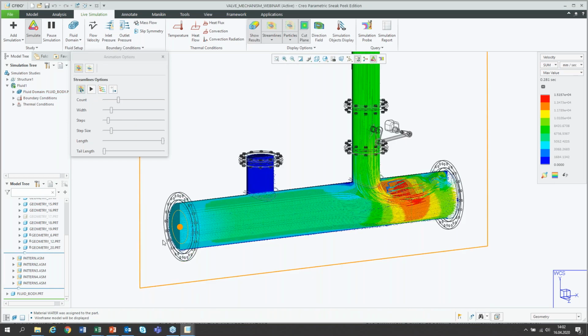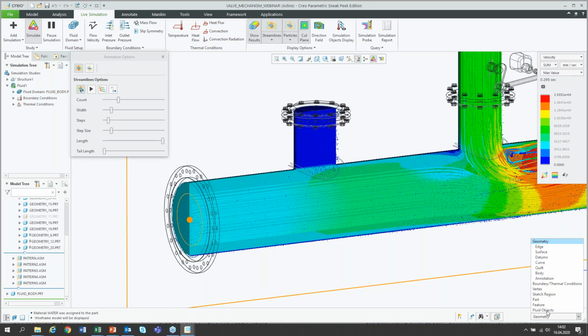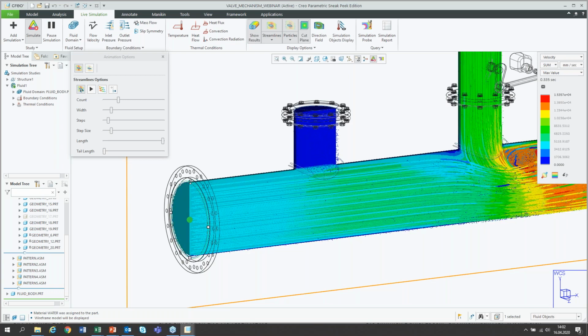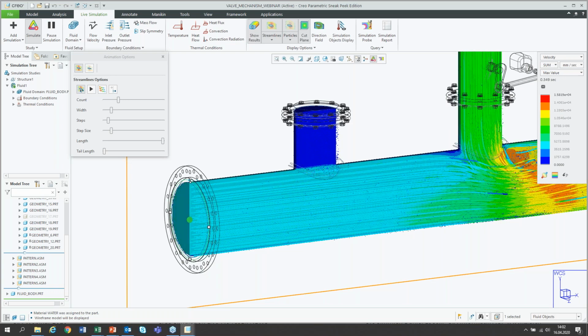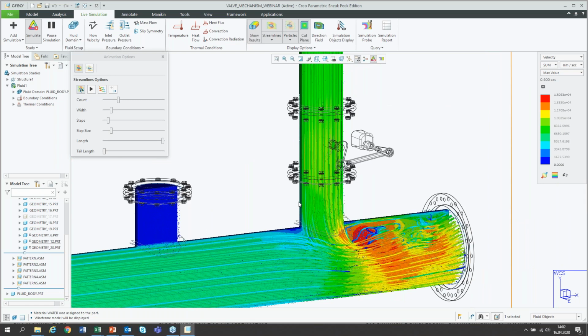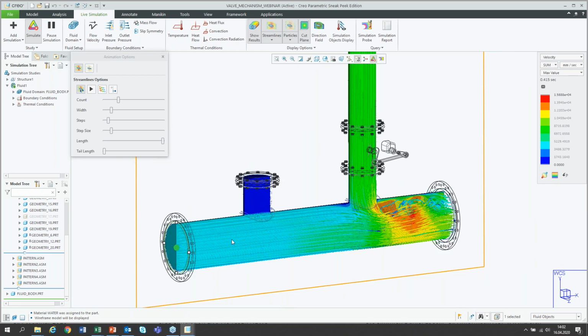And maybe in that area here, I'd like to change the area for the streamlines. Just hold down the shift button, not the switch button. Okay, and I can see all over my diameter all the streamlines, the behavior. Here, by clicking on that, I can also start with the streamlines here or here. Okay, I want to start here.